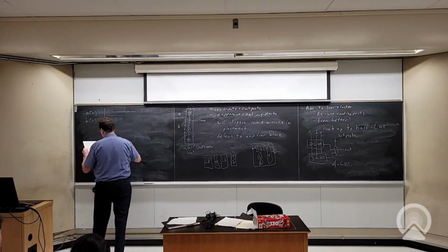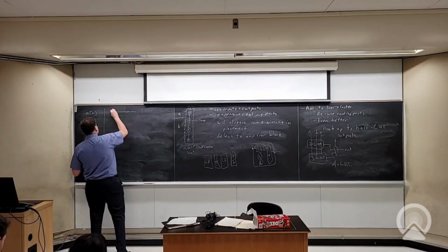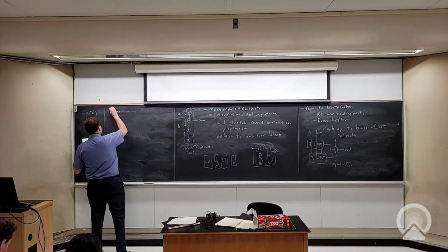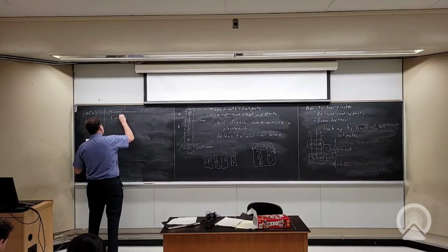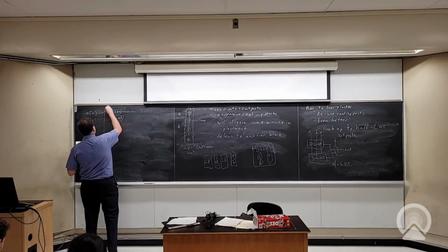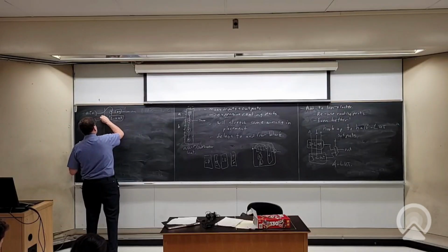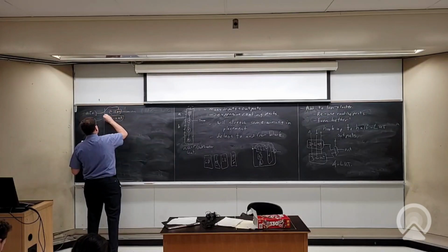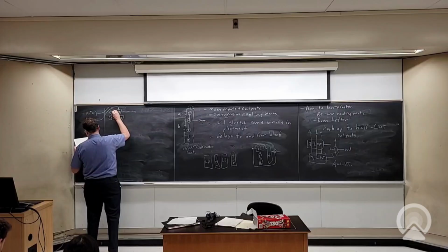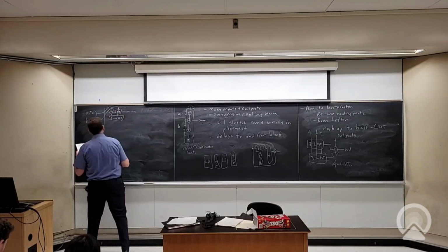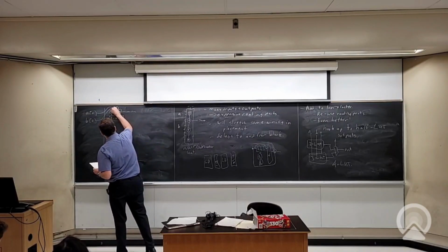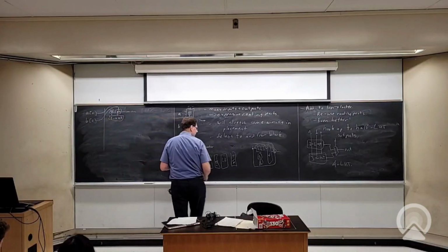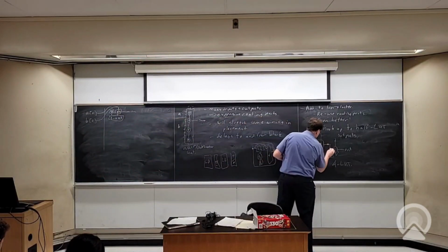Okay, so here's my logic block. I take a 4 LUT up here. I'm going to treat it as being 2. I've decomposed it into 2 3 LUTs. So I take A of 0 and send it in. Should have drawn it over to the other one. Okay, let's do this. A of 0 goes there, B of 0 goes there. So this was my 4 LUT, but basically I'm treating it as 2 3 LUTs that have these 2 outputs.